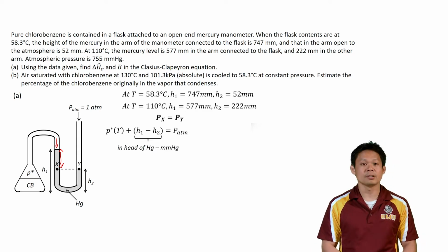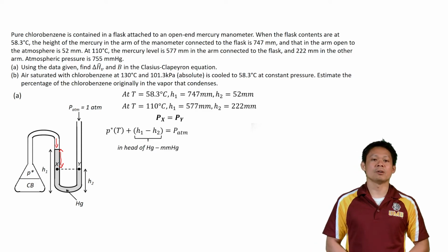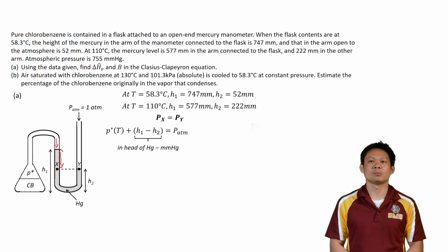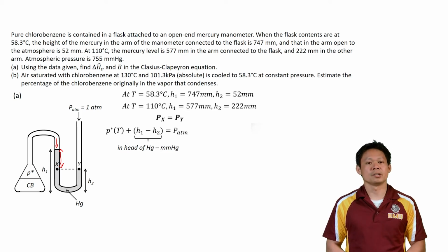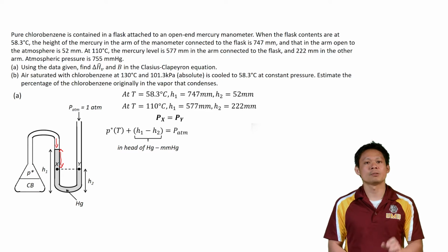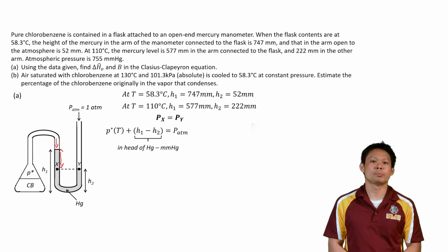Now what you see down here is that in terms of my pressure, all I did was take the heights and subtract one from the other, because we're going to do this entire problem in head of fluid, in this case head of mercury. So this is in millimeters of mercury. So hopefully here you see the power of using head of fluid to do pressures.